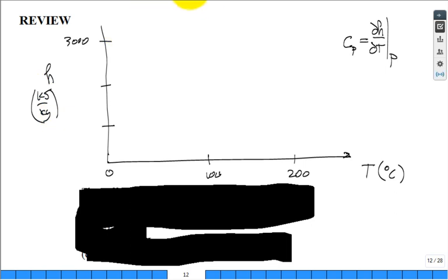So let's plot this starting out here. If I wanted to go up to a temperature of 100 degrees C, enthalpy was 420. So 420, 100, there's my line. Make sense? But then I got stuck at 100. As I added energy, H went up, up, up, but the temperature didn't go up. So it went straight up like this until it got to a value of 2677. Then, as I started to heat the saturated vapor, the temperature went up all the way to 200. It's only going to go up to 2877, so it's not as steep, but it gets up to 200.